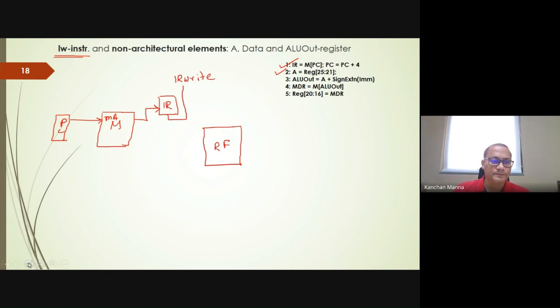So now, let's say this is register A. Okay. So we'll provide register address A. To calculate the effective address, we need the RS field from this. So RS field is coming here, and the width of this RS field is nothing but 5 bit. And here in the register file, we have 32 registers. So we have to identify one. Then the corresponding data would be available here.